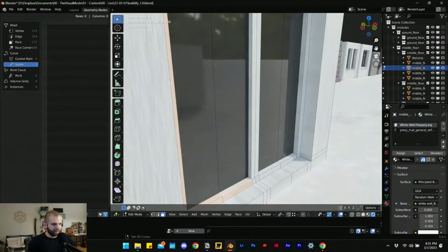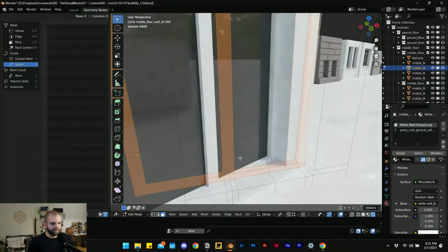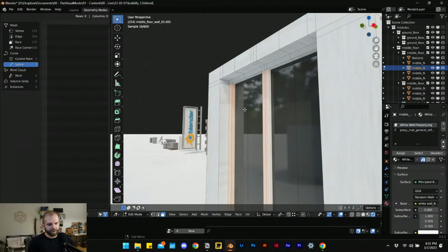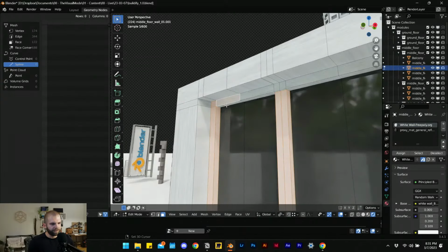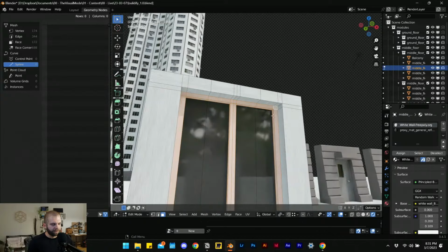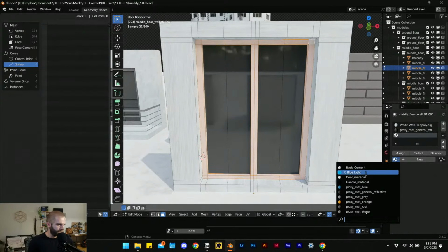It's easier if you start, I mean, I don't know if it's easier. Most of the time, before you extrude faces, like when I first set the cuts for the mullions, if you assign the material to it, when you then extrude it, it should carry through that material on the sides that it has on the front face. Although I've had that not be the case in certain circumstances, so a little bit of research I've got to do in that area to see why that is.